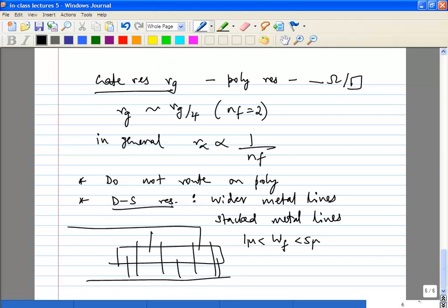Okay, try to keep it somewhere in between these two, 1 to 5 microns. If you have very large transistors, you would probably want to tend towards the larger limit, towards 5 microns. Otherwise your aspect ratio will get very weird. If you have very small transistors, let us say the overall width is only 10 microns, you're not going to gain a lot by making it into 1 micron fingers, you'll get a very long finger again. So you probably want to have a trade-off, but keep it somewhere in between these two numbers.